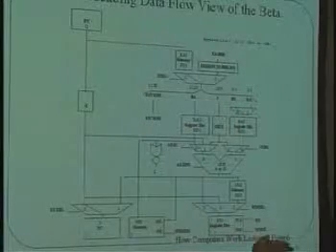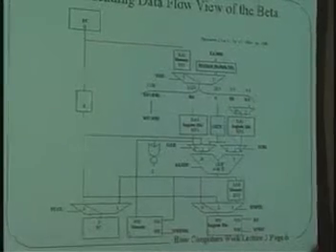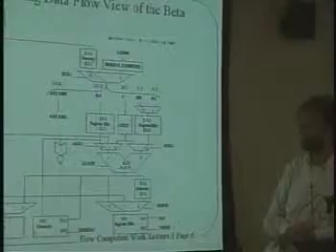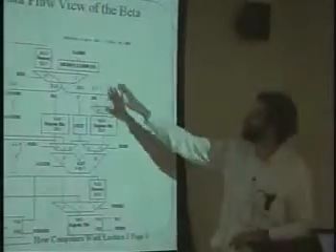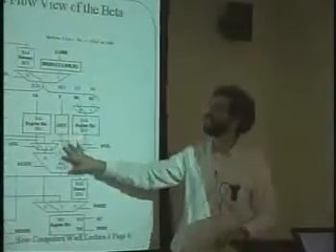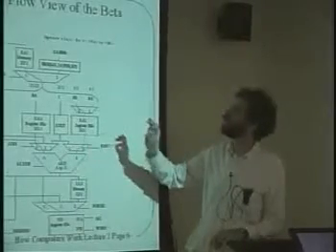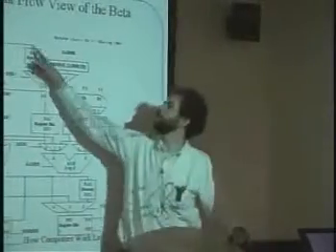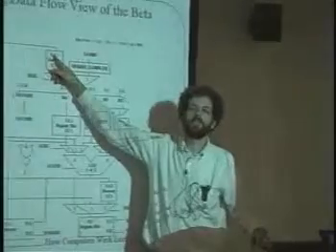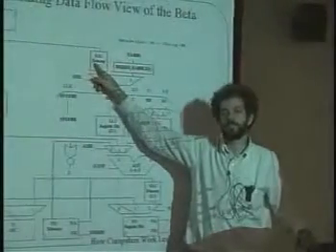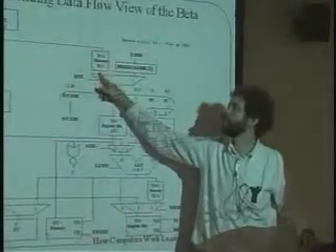Is it generally one clock cycle per opcode down there? Yes. So the data moves through all of this stuff, and then the clock goes off. Oh, that whole thing is one clock cycle? Yes. There is nothing here that holds up the data. If you remember, the model of the memory is that as soon as an address comes in here, it figures out what's at the location that the address points to and the data comes out.